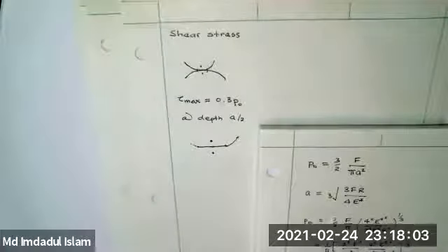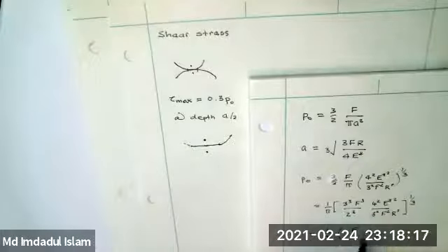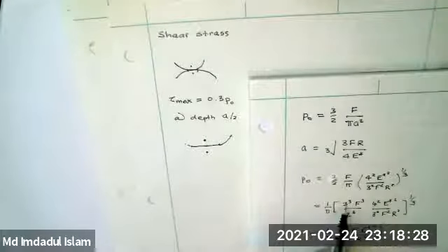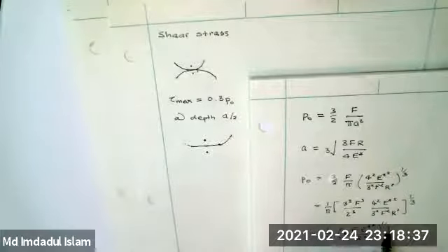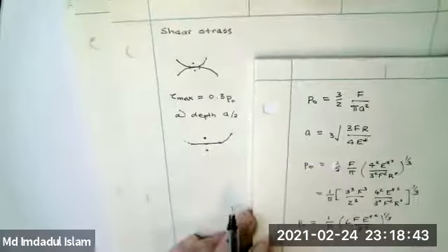Let's concentrate on the symbols first. We'll get the coefficient in a minute. That's F cubed, F squared, so it's just F. E star squared, there's no other E star, so it's just E star squared. And down the bottom, there's R squared. And there's some sort of numerical coefficient. Well, let's see. 3 squared, 3 cubed, that's just 3. 4 squared is 16, 2 cubed is 8, so that's 2, so the coefficient is 6. If you're going to use this form, you've got to get that numerical value correct.